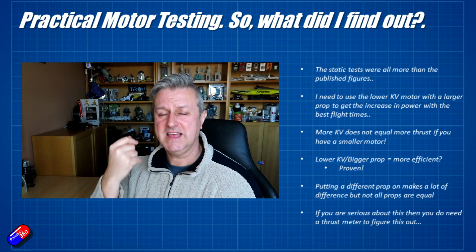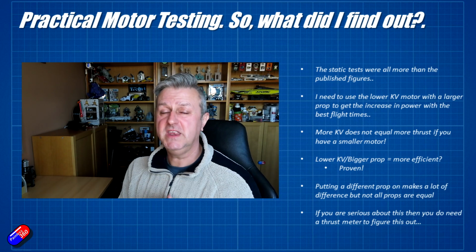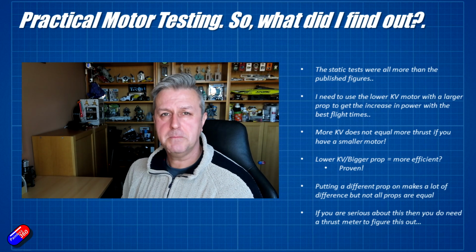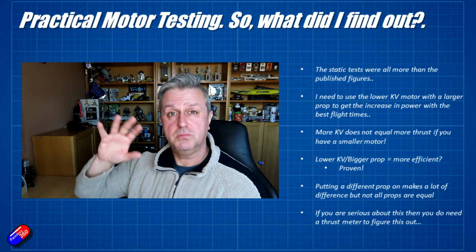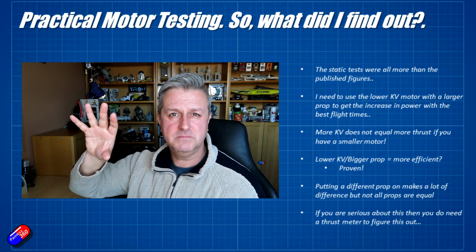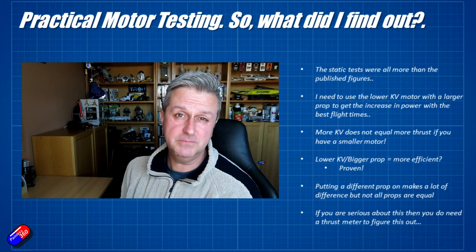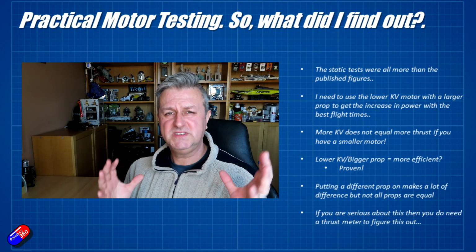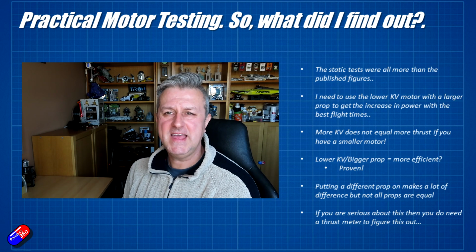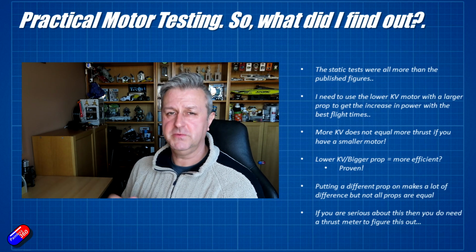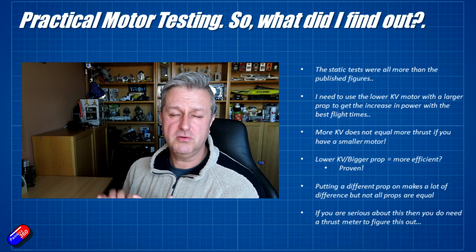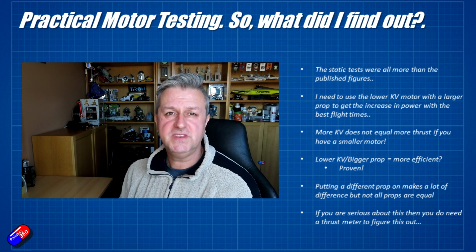But it also is handy if you are in that situation where you need to prop up, being able to look at that motor and prop combo with the battery that you've got in the thrust tables and figure out whether that's even possible. But what this has really proven to me is that there is no substitute, if you want to play with this stuff, to invest in a thrust meter and a watt meter and just run the data yourself.